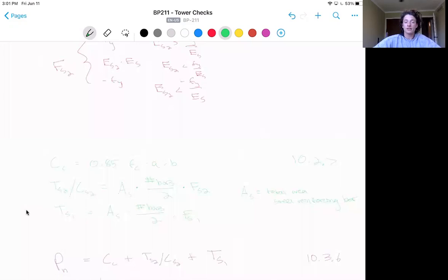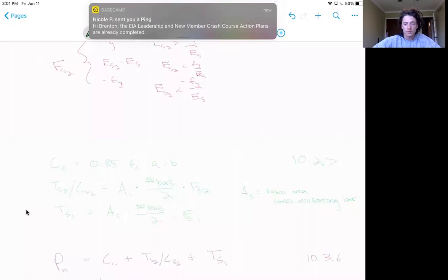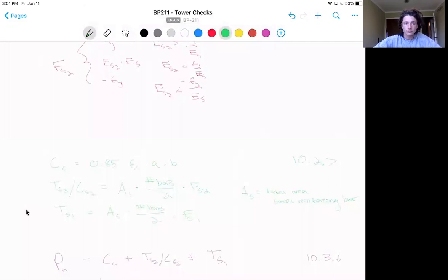We'll take the factored axial capacity as 0.65 multiplied by the nominal, because this is the most conservative value. This is a conservative assumption, and the load capacity reduction factor will be the first thing we examine if we need to sharpen the pencil and this calculation does not pass, because this 0.65 can and should probably go up to 0.9.